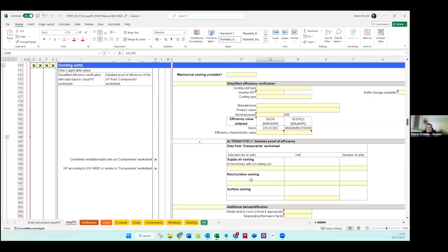So yeah, I don't see why not, but I would tend to steer multi-house type developments towards the standard approach, just because I think it makes more sense and it allows the block approach. If you've a terrace of say 6 or 7 dwellings, you don't have to do 6 or 7 individual PHPPs, whereas with the normal approach you can just do one PHPP and they're all done.